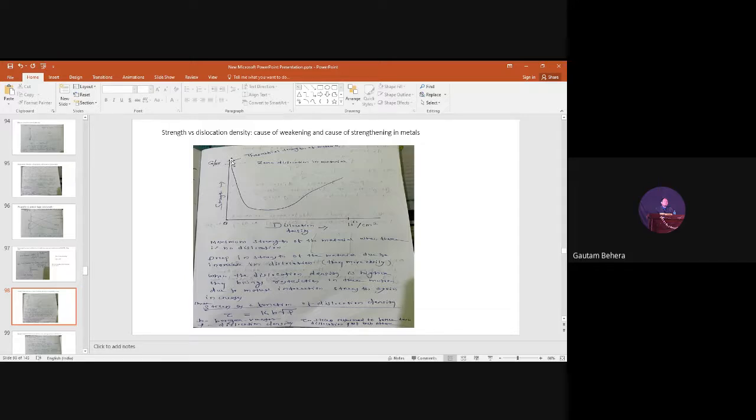So we do not have any dislocations, we do not have any crystalline defects or lattice defects. No grain boundary, no dislocations. So strength is nearly equal to theoretical shear strength, G by 2 pi, shear modulus by 2 pi, right? This is very high, gigapascal level. So you understand, when we have zero dislocations in a material, strength is maximum.